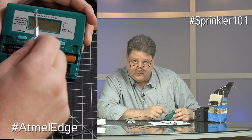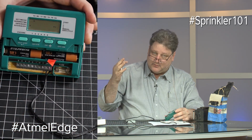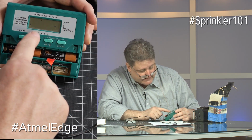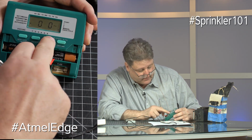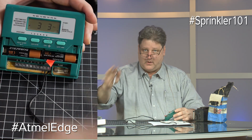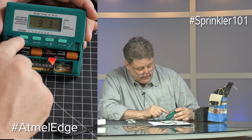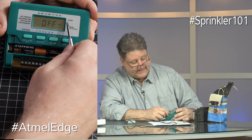Days on or off. Once again, for program 2, how often do you want it to work? Well, I think it's ridiculous to try to pick a day of the week. That's just me. So I go day station all the way around here. And instead of not 0, 0, not going on all, 3, 3, 3, which means every 3rd day, I'll water the lawn for 15 minutes, and it'll start doing that a few days from now. All right? Next step, the first time of that day.